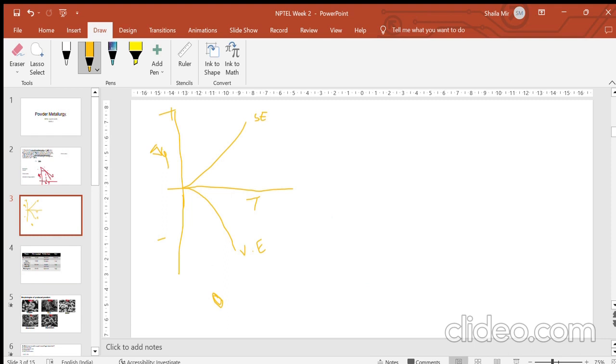The total Gibbs free energy is the summation of the surface energy and the volume energy, and the balance between the two will help us find the optimum place where the critical radius will be reached. So what is the critical radius?